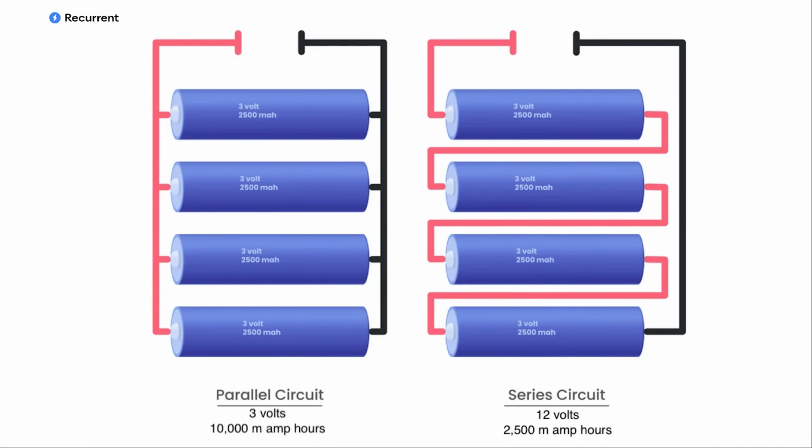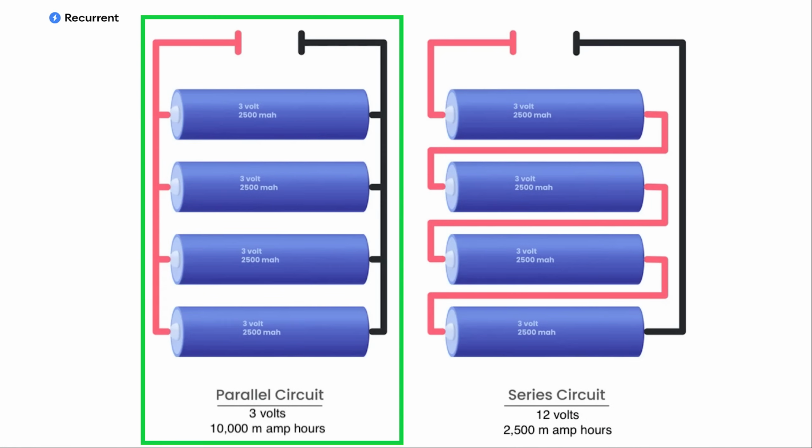The second issue that you've mentioned relates to what happens if I have lots of cells. Do they all behave the same? What happens when they start behaving differently? And the answer to that is it depends a little bit how they're connected. If they're connected in parallel, then they tend to self-balance a little bit. So if one of them gets to a higher voltage than another one, some current will flow into the one with the lower voltage, and they'll kind of regulate in that way. Again, that becomes a little bit more tricky when you've got flat voltages and hysteresis, just as a side point.